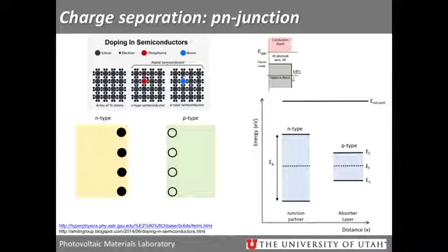Okay. So as we add atoms, impurities, or dopants into, so if we look at, this is for silicon, if we add a phosphorus atom, that is a group 5 element, so it has an extra valence electron, we essentially add an excess of electrons, and we can dope silicon N-type, which just means that you have extra free electrons.